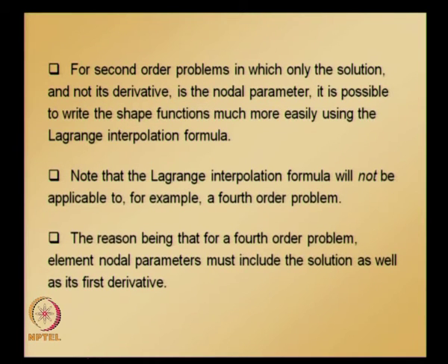The reason is simple: for a fourth order problem, nodal parameters must include the solution as well as its first derivative. So now let us look at, starting with a polynomial, how to derive shape functions for a quadratic element.